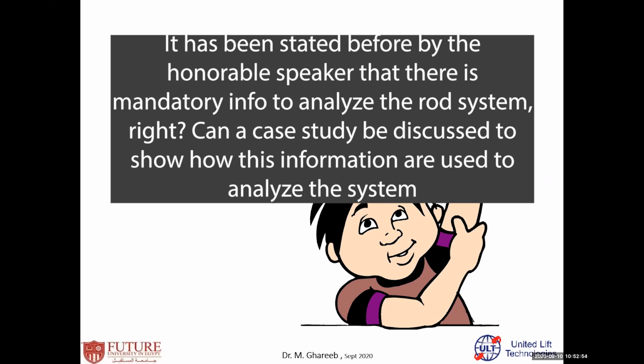One of the main important things, I see the majority of people start to be ignorant of, is the well inflow performance. You need to have in your hand the well inflow performance. Another information you need to have in hand is your well completions. What is your well completion? Another thing in hand, you need to have your current stroke length and your fluid properties. What type of fluid properties? Has my fluid properties changed, or is it the same?